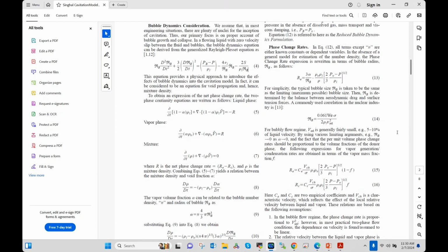Also, please note that our convergence is relative. It's not absolute. So that means we are comparing our convergence to the initial delta E that we created when we started the first iteration of the first time step. So when we talk about 1 order, that means we are comparing the ratio of that delta E term currently to how it was the first time. So if that drops by 1 order, that means that ratio has gone 10 times lower. So that's essentially how our convergence criteria works. I'm saying you do 3 orders for the steady state for the centrifugal pump, or 1 order for the transient simulation.